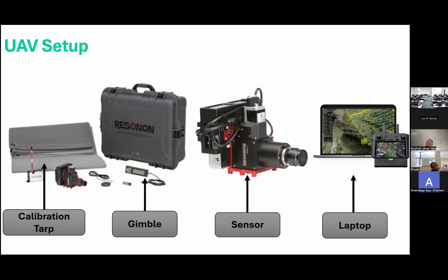All right, so when our sensor starts, we will take our UAV to the field and start flying the UAV. And when there is cloud, we have to stop, because it happened with me. We collected data, we came to the lab, and then we saw that in a big chunk of the field I don't have any image. All right.